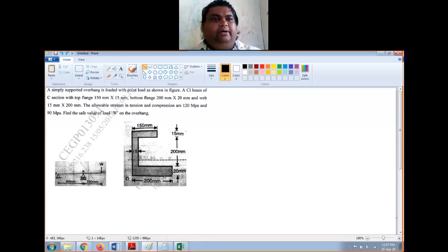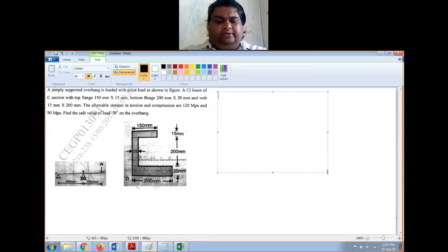So for finding y bar, we have this expression. First, I'll write the location of neutral axis NA, right? That is basically this axis. So with respect to the bottommost fiber, I'm doing it now. So how do we do this? Y bar is equal to, we did yesterday, summation of individual area into the distance from the reference to its own center of gravity, divided by total area.